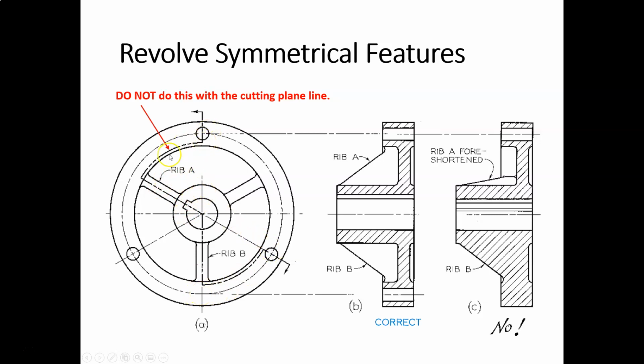So this cutting plane line is a horror show. We would never, ever, ever do this. I hope that they're just showing it for descriptive purposes to show exactly how the cuts are made to generate this view. Okay. Also, suffice it to say, none of the parts that you're going to be working on involves this kind of construction.